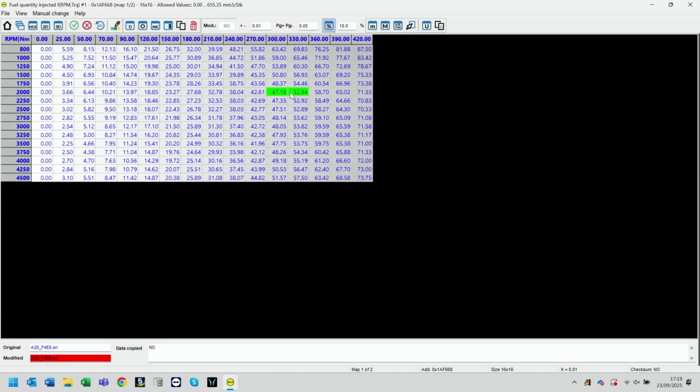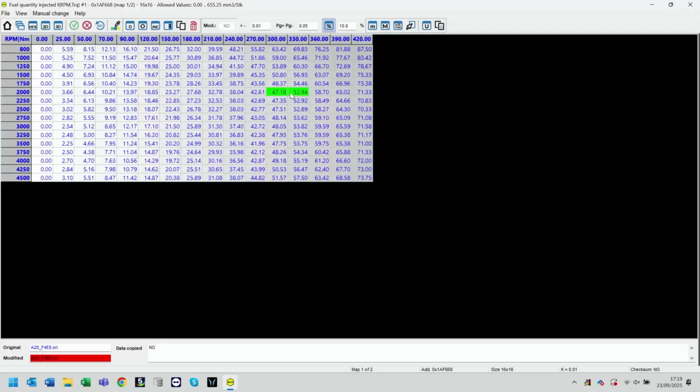So when we move on to our next set of maps, we've got a benchmark now, not only for the amount of torque and a reference point for RPM, but we can start to look at the amount of fuel. So things like your rail pressure maps and your turbo maps we'll look at shortly all have fuel quantities as their axis. Okay, I got you. So you're starting to marry these different things together. Unfortunately, not every map just uses torque as the axis. That would make life very easy. Sure. But it allows us to pull those values together. You can use the axis from one map into the next map, into the next map. Yes, as that data point to reference and to build up an understanding of the stock strategy.